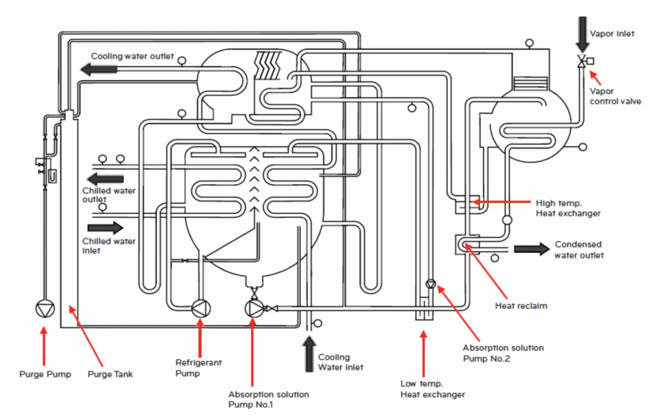In the low-temperature regenerator, hot refrigerant vapor which is separated out of the high-temperature regenerator passes through heat transfer tubes, heating the intermediate solution to make it more concentrated, about 63%. It is the most concentrated absorption solution and is called concentrated solution.